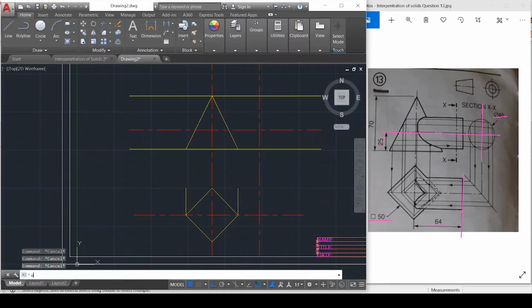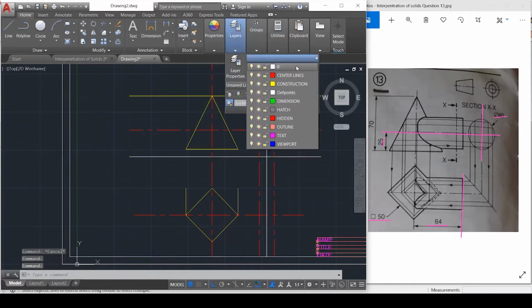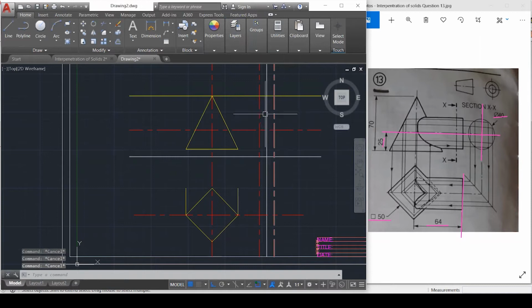So I'm going to offset 10 to give myself a frame line, and then another 10 to where the drawing will start. So I'm going to do that down here also to give myself a frame line down there. Yeah. So we know that this is the base for that drawing. We know that this and this, I can put those into layer 0, for those are my frame lines. I know that this is going to be the edge of where my cylinder stops, and this is going to be the edge where my circle starts.